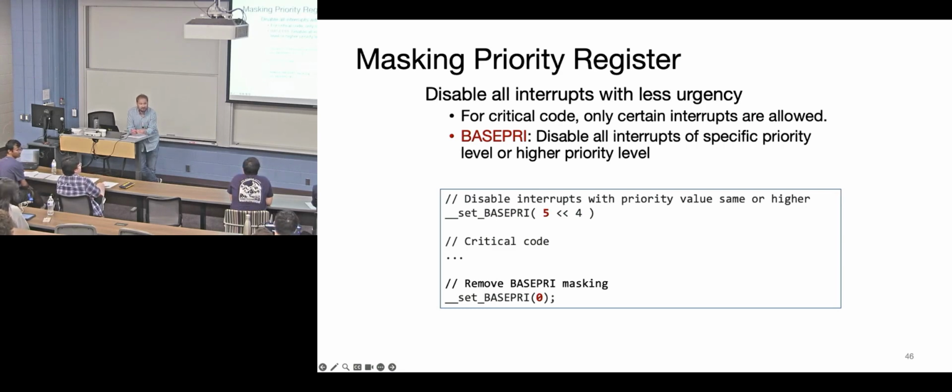And can an interrupt hold this information too? Like we're in the middle of an interrupt and we're at a critical piece of that interrupt. Yeah, we can just add those 2 lines of code and then no other interrupt with lower priority. Correct. That might be an indication that you set up your interrupt priorities incorrectly, right? Because then what you're basically saying is every time I write this code, I want it to be more important than something else, but you could have gone and just set your interrupt priority and your sub-priorities correctly.